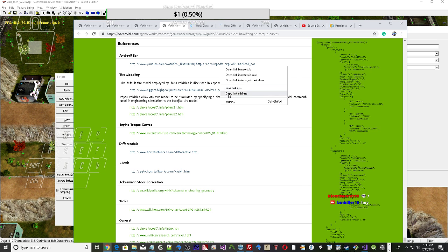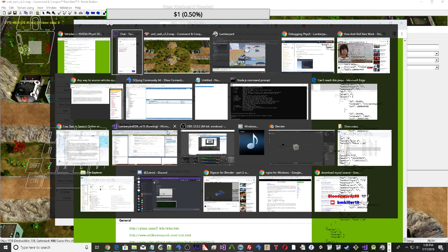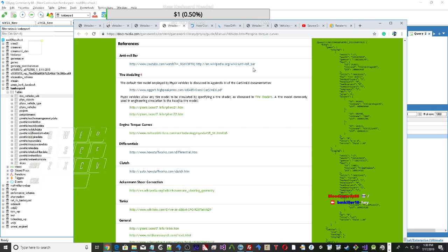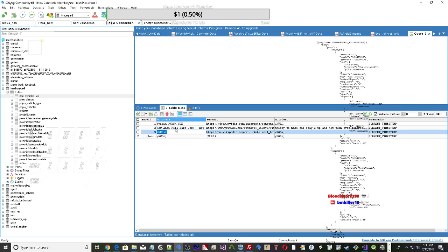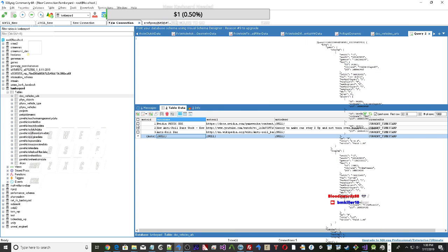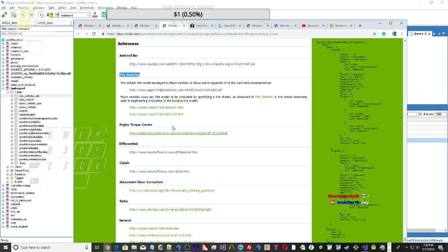Advanced Concepts. Vehicle Creation. This section discusses the configuration of vehicle simulation data and describes how to set up an actor that will represent the vehicle in the PhysX SDK. Section Introduction to Vehicle Creation identified 3 distinct phases of vehicle configuration: configuration of wheel simulation data, configuration of drive simulation data, and actor configuration. Each of these phases is discussed in turn.